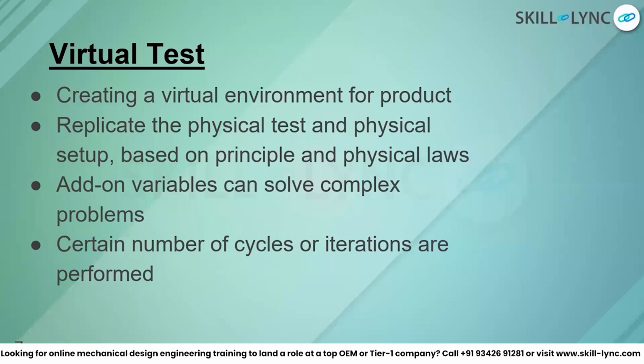Say, for example, we see that the convergence has been reached after a certain iteration, and the result is not changing, when we're talking about the steady state simulation. So there should be some criteria where we can take those results. When we are solving the equations virtually, we need to understand at what point we should take the results, or what is the extent where we can stop the simulation, and we can take those results for our reference.